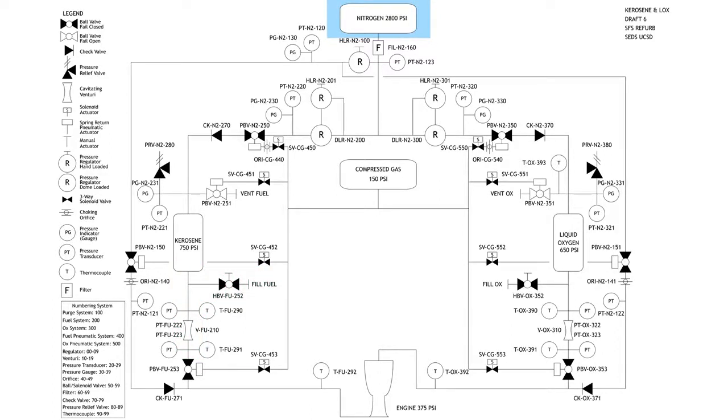Is there a reason you pick nitrogen over like helium? So yes, helium's way more expensive. It's about $960 per bottle. Nitrogen's like 80. And nitrogen is an inert gas just like it, and it's a little bit heavier than helium. Helium flows a lot faster. And helium creates a lot of dangerous situations, especially with pressure relief valves. So if you were to open a pressure relief valve with helium versus gaseous nitrogen, when it breaks open, it could cause a lot of damage because it wants to flow out so fast. And so nitrogen is a little bit safer because it flows a lot slower.